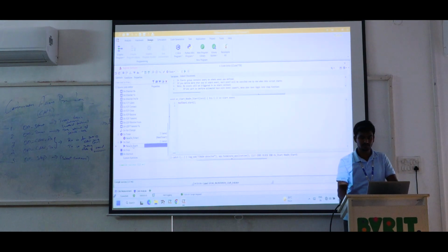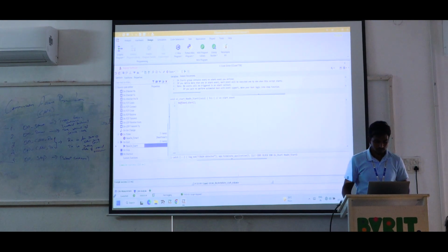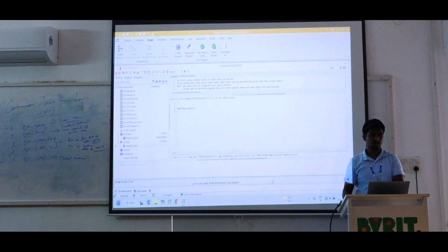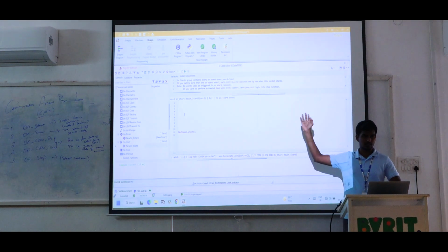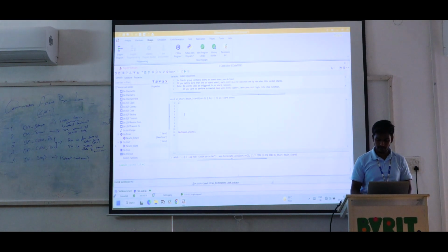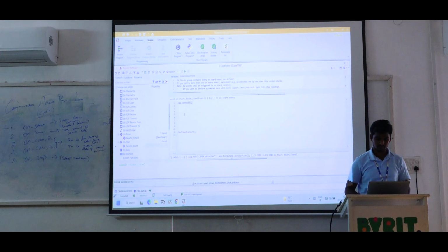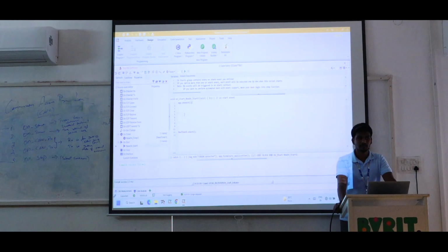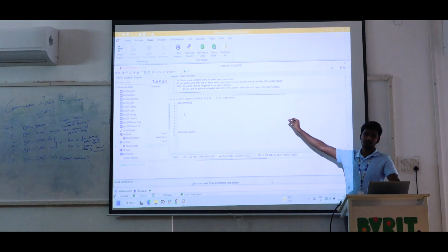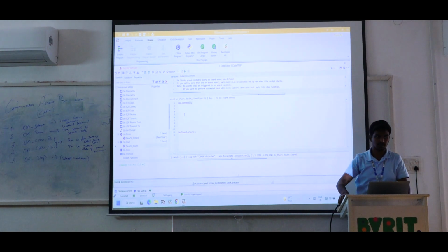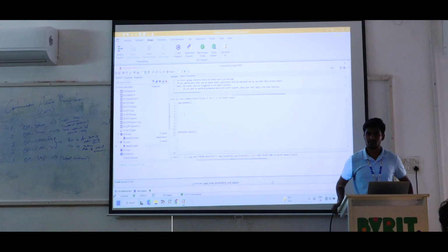Go to on start. Already we wrote only one line of code, which is timer.start, right? So give some spaces, go to the first line. Our initial condition is to turn on the simulation. So please type app.connect. Just type app.con and you will get the code completion. Use the enter key to get the lines.